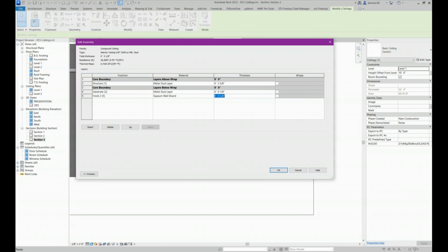You can just draw marker lines and then create a floor panel out of them. So we don't consider these layers because you can create it multiple ways. But for a really nice model, architecturally accurate at least, and to ensure the heights of your joists are correct, I like to put them in.